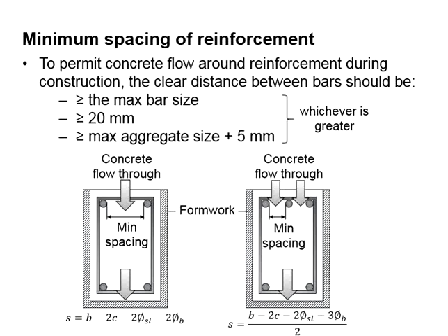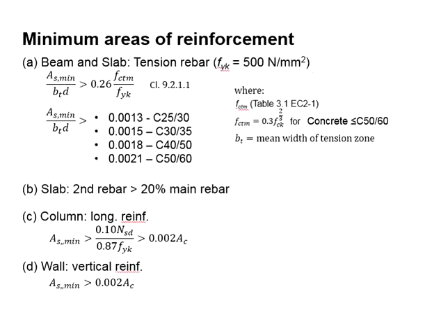Therefore, most likely you will not be asked to determine the minimum spacing for the slab design. Minimum bar area, probably, as you're going to expect that sometimes the reinforcement provided may be less than the minimum bar areas required. In order to prevent providing the reinforcement less than the minimum bar area, normally you should check for the minimum bar area.